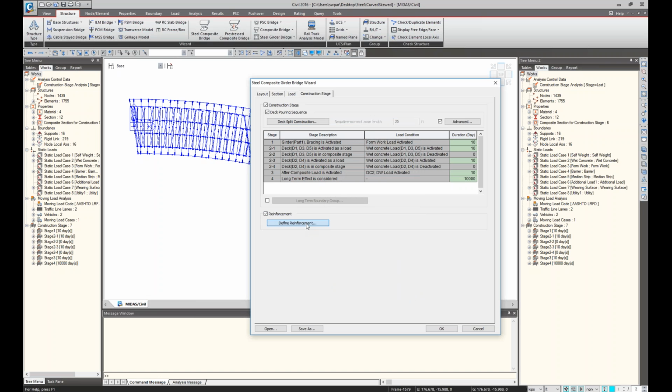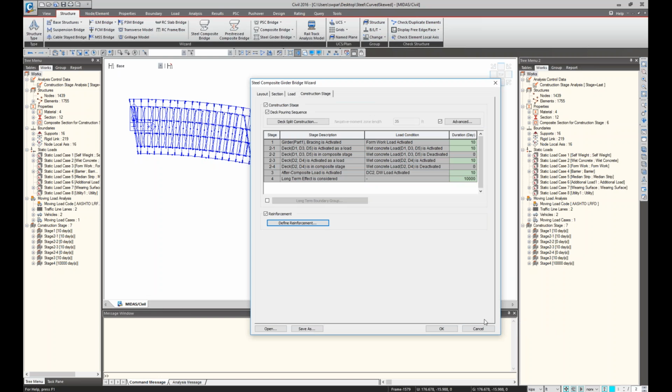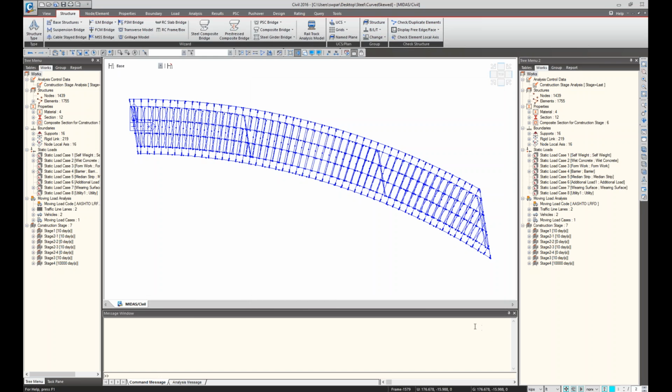When you look at the reinforcement, under negative moment regions, at the top portions, if there is only concrete, it cannot resist the tension from the moment, right? So in that case, you put the steel reinforcement here, and then when you run the analysis, the program can consider this steel reinforcement part in your result values. Many people do not know these functions.